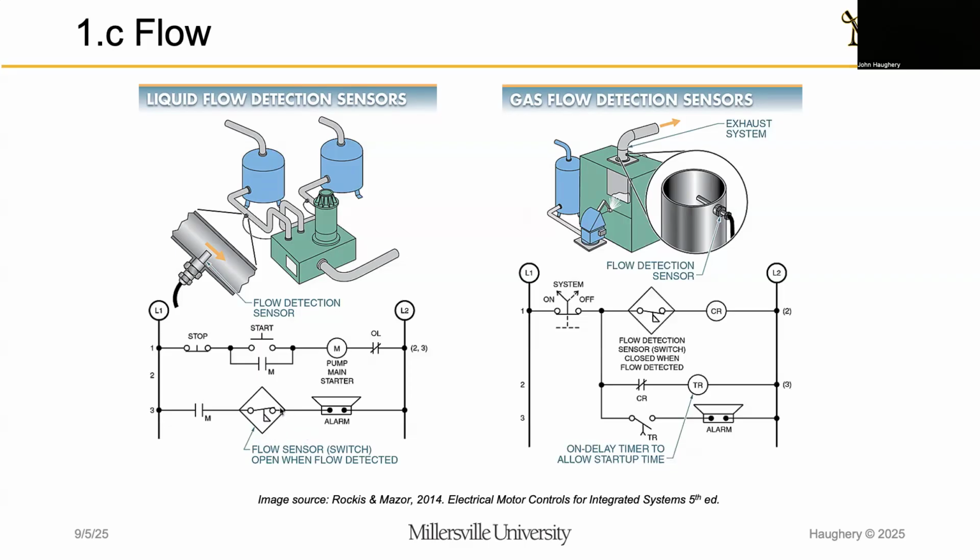The weather vane piece is illustrating that flow or flapper action that's going to happen. The diamond that we see around the entire symbol is indicating solid state. And so that's the case for any of the sensors we're talking about in this slide deck being solid state. Whenever we put a diamond around the symbol, that's telling us that it's a solid state device, no moving parts. And so we can use the typical limit switch style symbol, attach on this vane or flapper hanging off the bottom. And then, of course, we can put a diamond around it to indicate it's solid state.